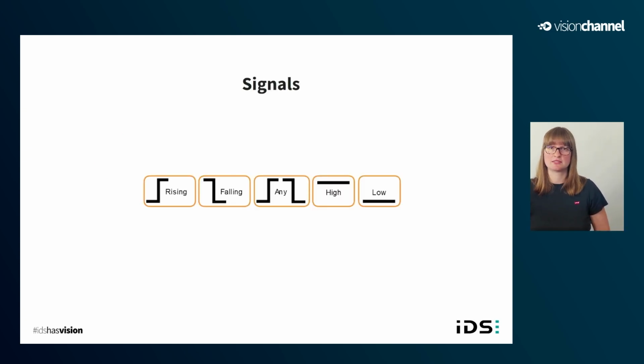Depending on the source, the signal is either a short pulse triggered by an event, like a start signal, or a continuous signal, for example, while something is active or inactive. Likewise, some targets need a pulse as a signal, for example, to count up a counter, or a permanent signal, for example, for a hardware output. Some targets that need a pulse can also process the status change of a continuous signal, letting you choose between detecting rising, falling, or both edges.